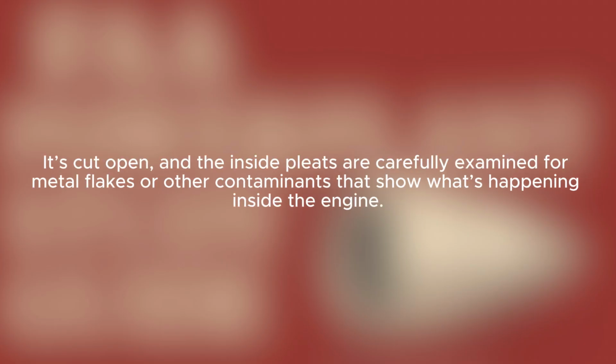What's done with an oil filter after it's removed from the engine? It's cut open, and the inside pleats are carefully examined for metal flakes or other contaminants that show what's happening inside the engine.